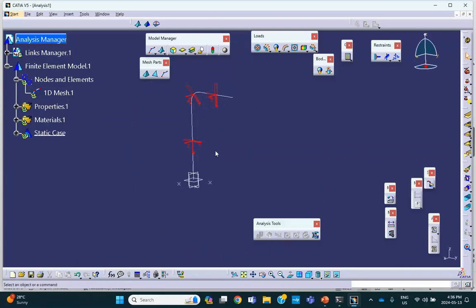Now, this is not random, but you might say, well, which point do I use then? How do I create that point? That is not random, but you have to understand the significance of the orientation point. If all our beams are circular in cross section or hollow tubes, it makes no difference. You don't have to worry about it.